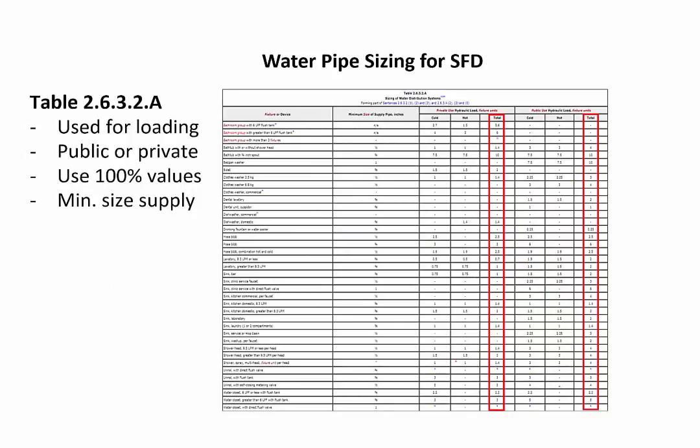Always use 100% loads, so we use the total loads for all fixtures listed. So whether it's the single family simplified method, or we're using some commercial or average pressure loss methods, we always use 100% of the totals. These 75% individual loads that are provided are for detailed engineered methods. So for installers, inspectors, 100% loading is what is going to be used for the codebook methods. This table also is used to determine minimum size of supply pipes. So let's take a closer look at table 2632A.